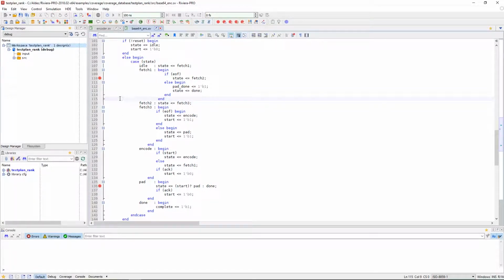Breakpoints are used to halt simulation when a condition or state is reached for signals, code, assertions, or covers. Breakpoints should be used to create breaks in simulation at specific windows and conditions of testing. They can be helpful to identify functionality of IP or new designs. Riviera-PRO has the capability to set breakpoints and manage them within their corresponding windows.